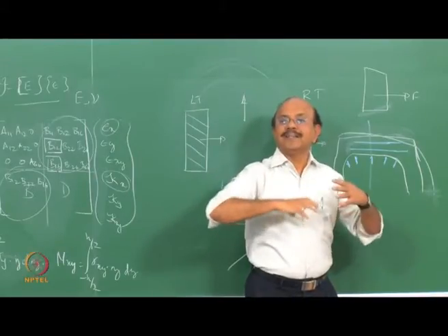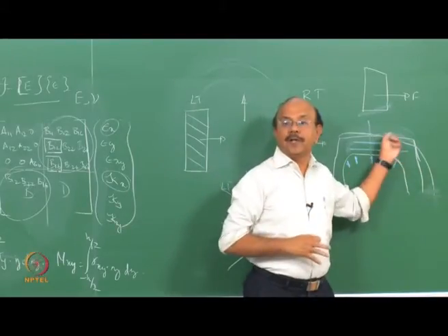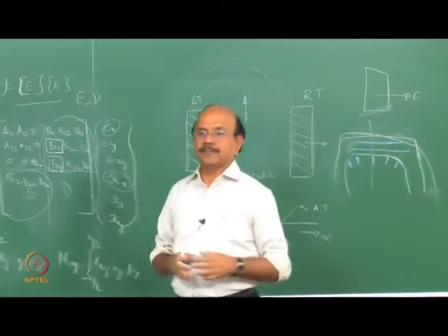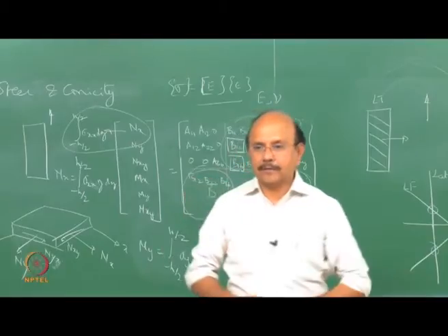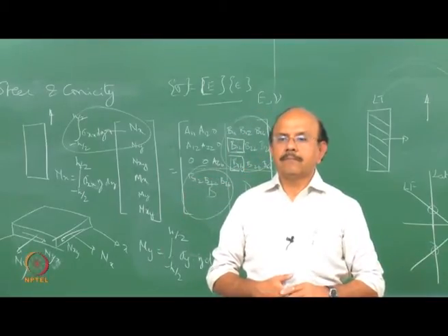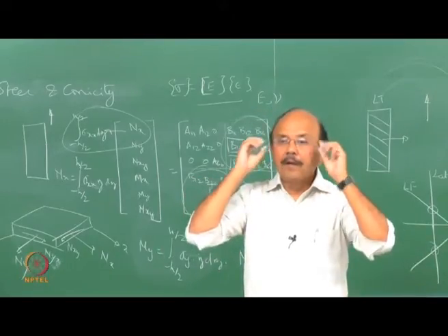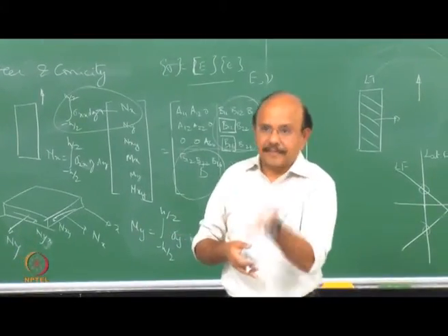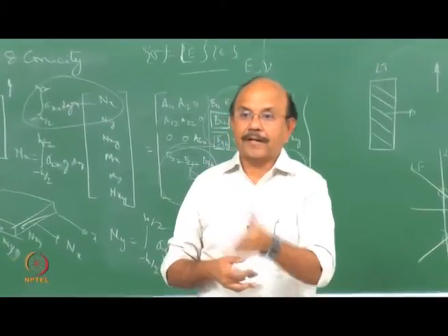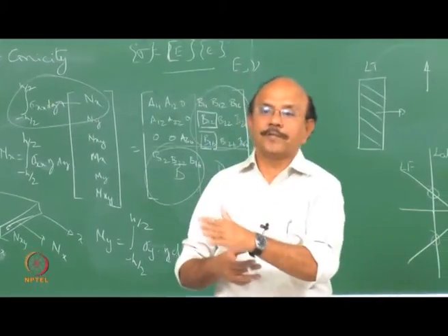In other words, the pressure distributions on either side are not going to be the same. So it's as if there's a cone sitting and then rolling. At any time when the wheel and tire interact with the road, the surface is always flat, right? Correct, agree with you. The surface is flat, but the pressure distributions are not going to be the same.